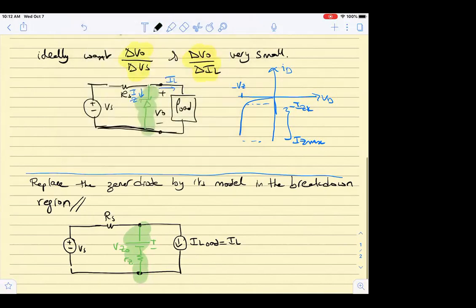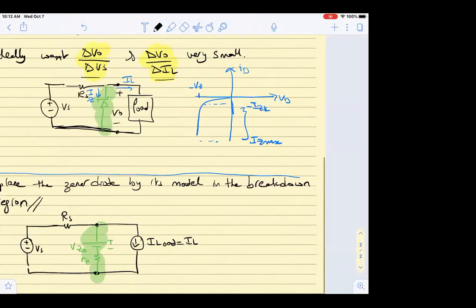So let us see now in what follows. We are going to do a theoretical derivation for the two sensitivity parameters that we talked about here, and then we will take an example. So what does the theoretical derivation tell me? To make it simpler, we take this circuit which has a voltage source and a resistor, and another voltage source and a resistor, as well as the load current source. We are going to make the circuit all current sources, meaning we make the Norton equivalent of each component. So the first branch we have is VS RS.